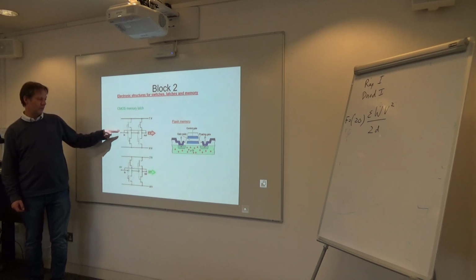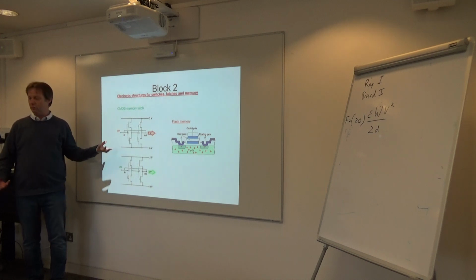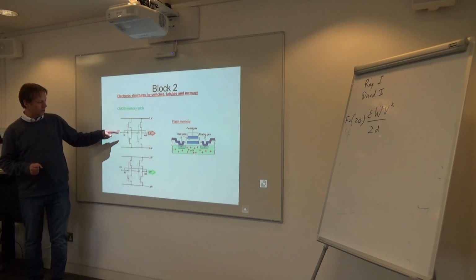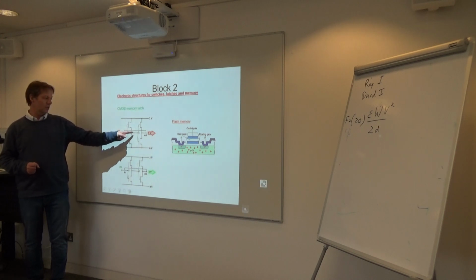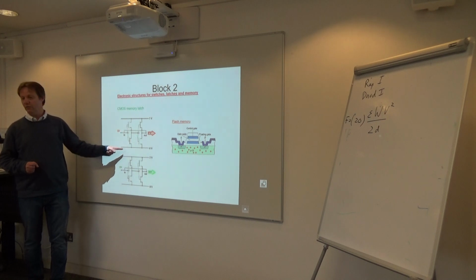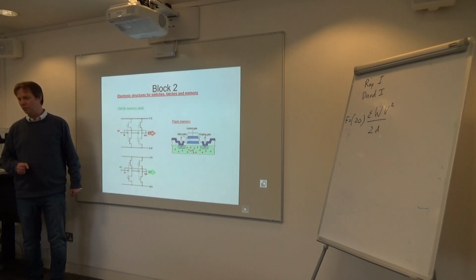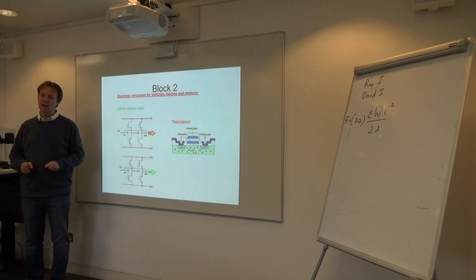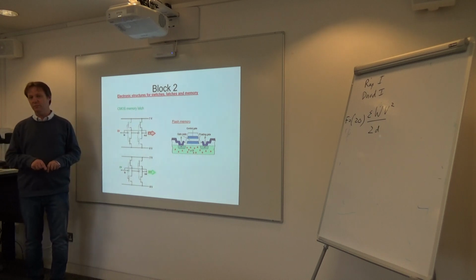And the effect of that is, if that's a positive bias, they'll say everything's running from the 5 volt supply, as shown in this example. You get 5 volts in there. At the output of the first inverter, because that switch has been switched on, that connects the output terminal to your 0 volts rail. So 5 volts in gives you 0 volts out, and conversely 0 volts in gives you 5 volts out. And in logic terms, you've taken your 1 and you've inverted it to a 0.